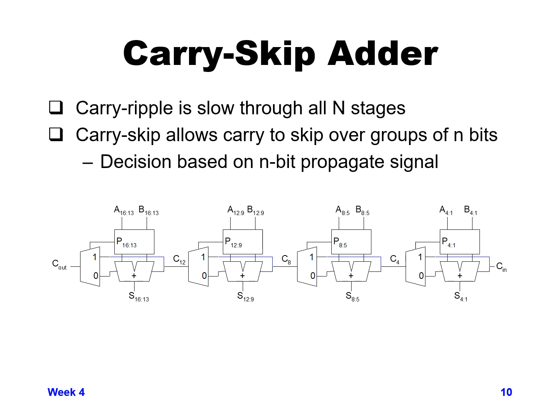And then we go through that delay and we get propagate or our carry out for bit 8, and it just goes through a single delay. It's got the propagate 12 through 9 waiting for bit 8 already, so it can go there, get compared, and produce a carry out for bit 12 with just a single delay.